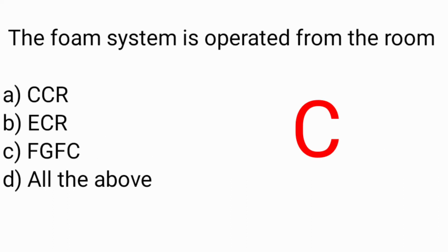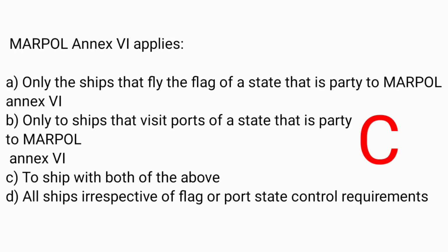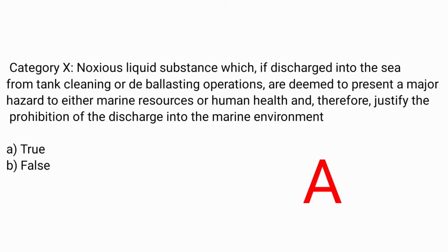The foam system is operated from the room. Answer C, FGFC. MARPOL Annex 6 applies. Answer C, to ships with both of the above. Category X noxious liquid substances, which, if discharged into the sea from tank cleaning or deballasting operations, are deemed to present a major hazard to either marine resources or human health and therefore justify the prohibition of the discharge into the marine environment. Answer A, true.